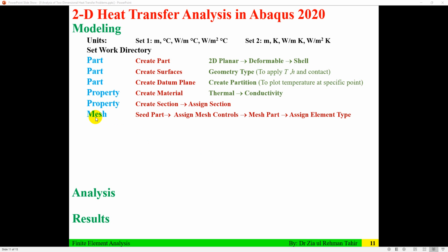Next step is mesh. So it is seed part, assign mesh control, mesh part, and assign element type. And this is required for all these three.